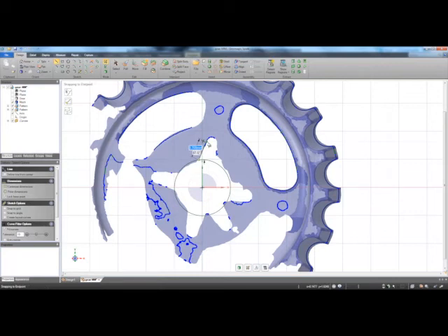So I just left mouse button and place that line, escape to stop that line, and then I can build up my teeth. So I'll just quickly create all these. It doesn't have to be perfect. We can always adjust those teeth in a second. But you can also do, like I said, many ways to create this process and create those teeth. This just being one of them. You can also pattern those teeth around. So copy them and rotate them, whatever you want to do.